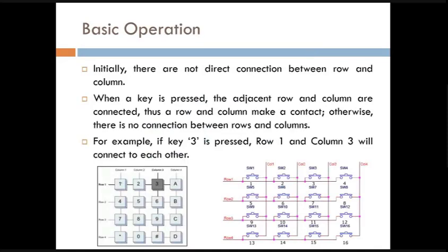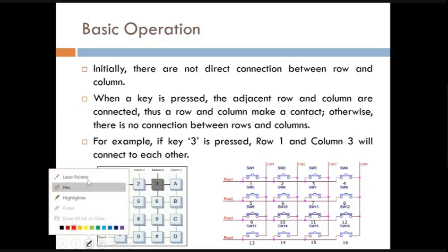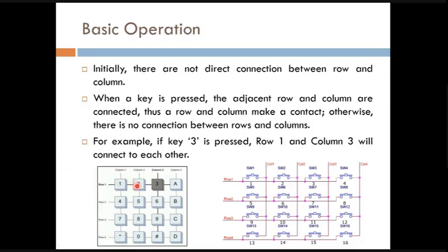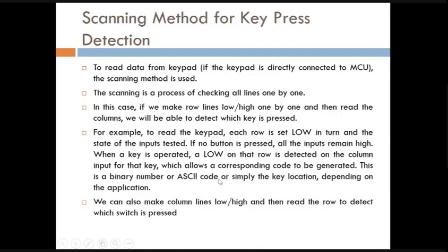So this is location 1, location 2, location 3, location 4. Location 4 is actually for input A. And then you go for location 5, location 6, location 7, location 8. Location 8 will return the character that you pressed, which is actually character B. So it is not giving the actual value of the keypad, only the location number.